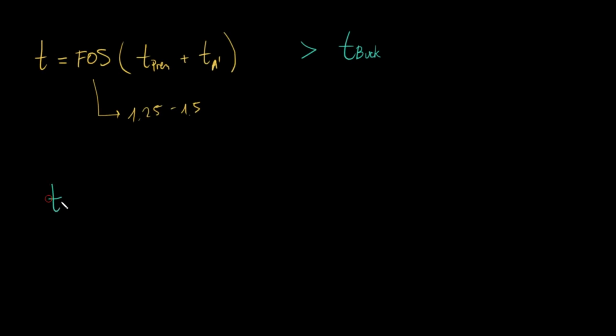We calculate the buckling thickness in the following way. This formula doesn't appear explicitly in Fleeman. It's just a combination of two formulas, but I think it's clearer if I show it to you this way. So it's 2 times the total axial forces over Young's modulus, pi, and the thickness we just calculated.